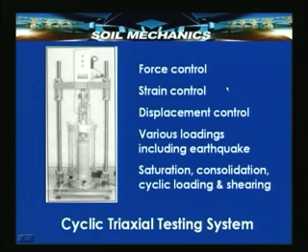You can apply load in terms of forces and have control over the force applied. You can apply the load indirectly by inducing a strain, as in a direct shear test, where we induce strain and produce the shear forces appropriately. So, this could be strain controlled, it could be force controlled, it could be displacement controlled also. And different types of loadings are permissible because this is usually digitally computer controlled.